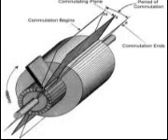The drum-type armature. Enough to provide reasonable brush life. Since the contact resistance of carbon is fairly high, the brush must be quite large to provide a large area of contact. The commutator surface is highly polished to reduce friction as much as possible. Oil or grease must never be used on a commutator, and extreme care must be used when cleaning it to avoid marring or scratching the surface.